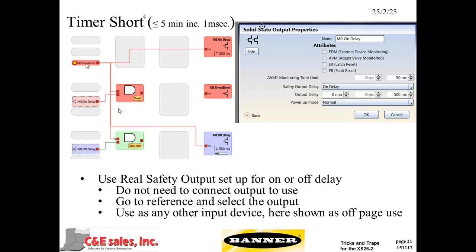I can use, remember we talked about references. I can look at the reference value on these outputs, in this particular case, the on delay and the off delay. So look at the reference values and put that into some kind of a logic block that says, yes, the timer event is taking place, and this is the status of the time delay variable output.